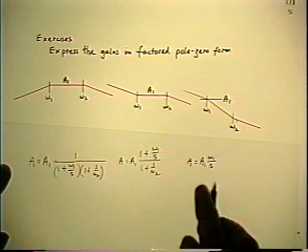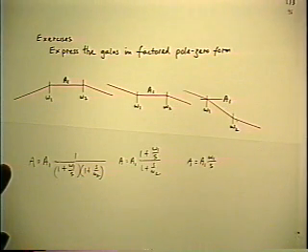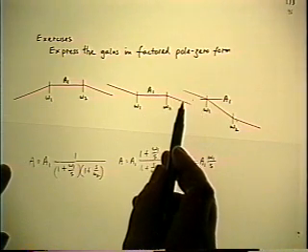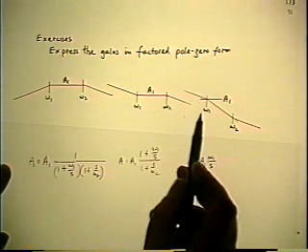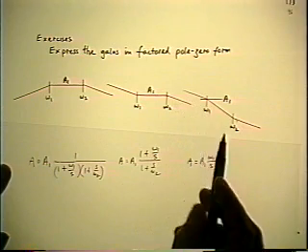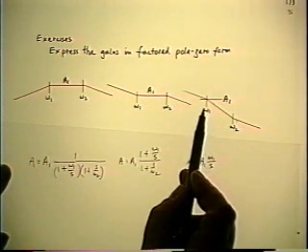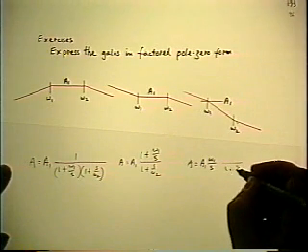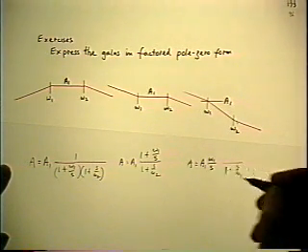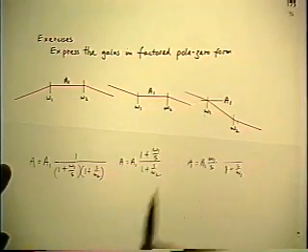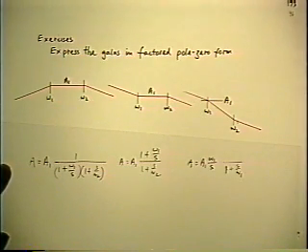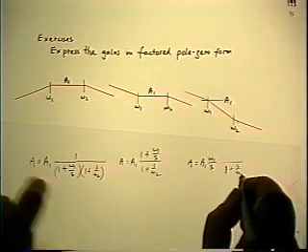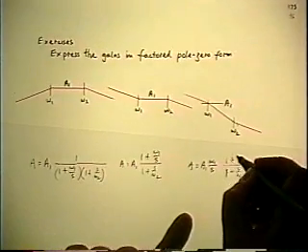And from there, it's nothing new. Because now we've identified the left-hand asymptote, and all you do is look up in frequency. Nothing happens going down. If you look up in frequency, you see a normal pole at omega 1. It just happens to be the same frequency we already used as reference. And finally, a concave upwards corner, which is a normal zero at omega 2.